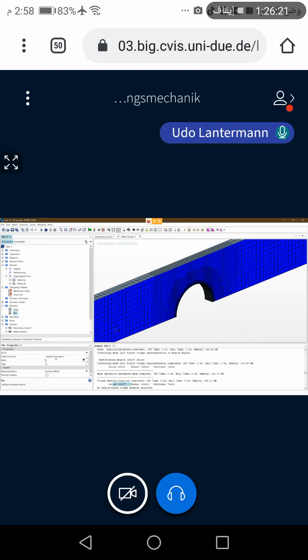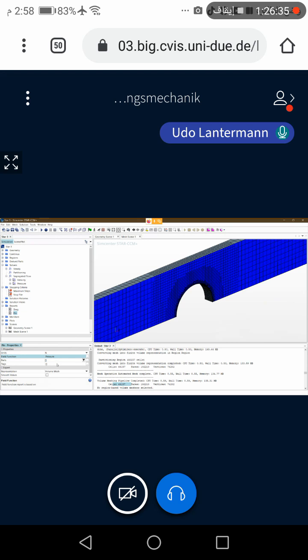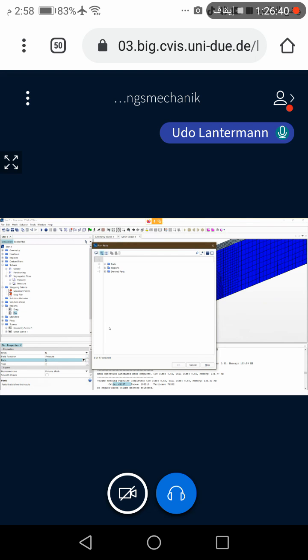So now we have to select our function. As I called it pressure, here we want to choose the pressure, so click on function, and then P, where P is pressure. Okay, and we have to define our parts where it is calculated, and this should be the pressure integration at the inlet, so regions, and choose inlet. And that's all.